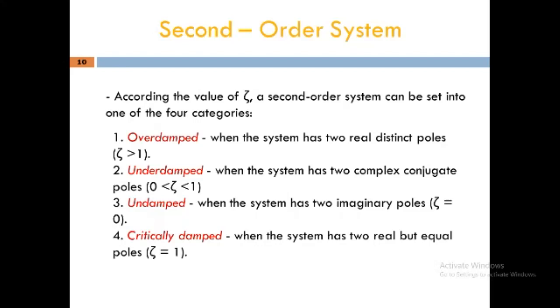The solution may be obtained by integrating each side of the equation and by adding a constant, and the integration deals with the ln, means log of Vc is equal to minus 1 upon RC of t plus log of D. So the capacitor voltage will be identified as D into e to the power minus t upon RC, and hence the constant D can be evaluated by substituting into the original differential equation and identifying the value at t equal to 0.